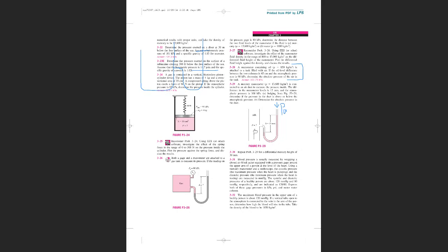I have 25 students inside. It's above, by logic. It is above because it is pushing the fluid. You are right. Okay, it is above, because if it were below atmospheric, the fluid of the manometer would have gone into the tube, right?